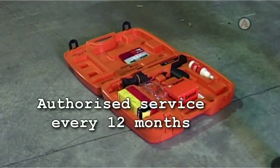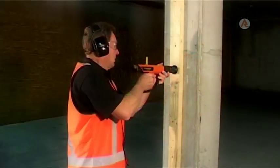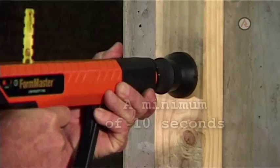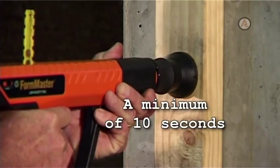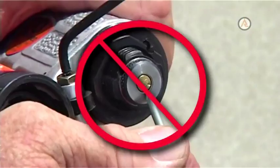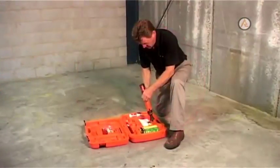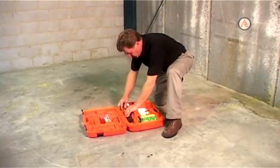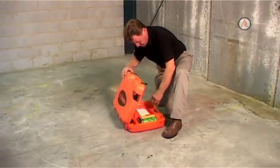The Australian standard for powder-actuated tools requires that all tools be serviced at least once every 12 months by an authorised service centre. If a misfire occurs, the tool must be held firmly against the work surface for a minimum of 10 seconds. When the tool is removed, the power load should then be extracted. If the power load is jammed, do not attempt to prise it clear. If the power load cannot be removed, the tool should be locked in its case and returned to an approved powder-actuated tool service centre.